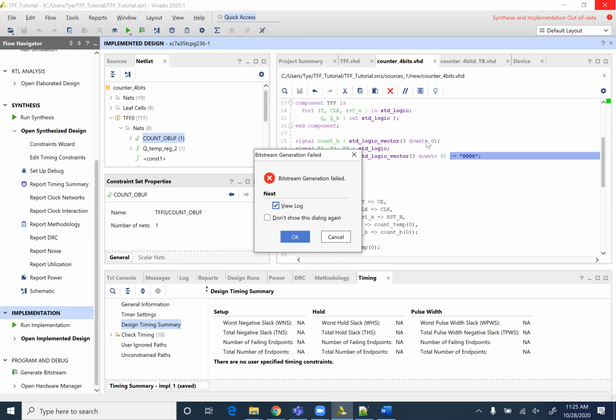But we can write to a memory that is used on boot up to automatically string those connections back together. This is useful if you design a product that may run out of batteries. You don't want to have them have Vivado and be able to plug it in and reboot the FPGA. That is not really a good product. So what you do is you save it into a memory, and on boot up it automatically loads from there.